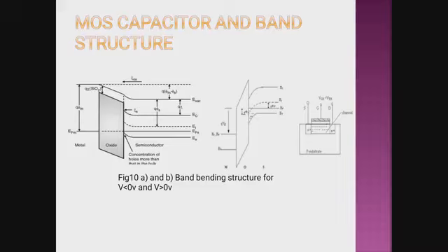While the metal is at negative potential with respect to the substrate, here suppose a P type substrate has been chosen, then the Fermi level moves up by the amount of the applied voltage externally, for case 1 when V is less than 0.